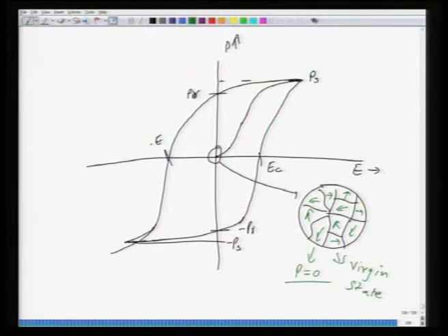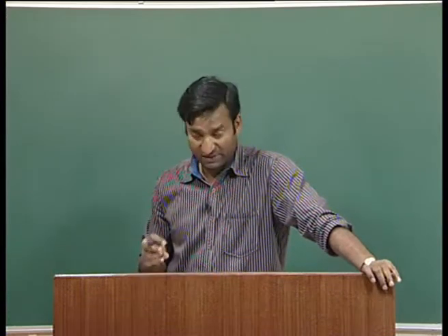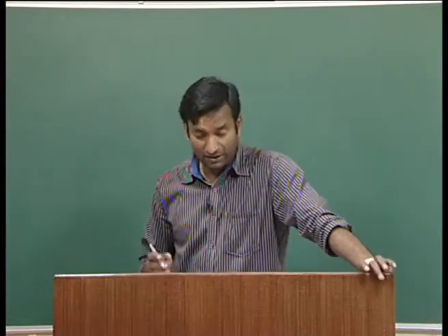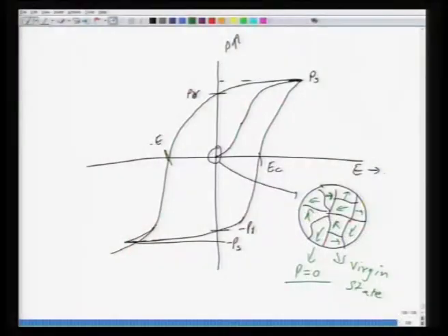But the moment you start poling it, you have formation of new domains. Now, this does not happen as, we will see, in magnetic materials. In ferroelectric materials, each time you do the polarization, it is always the nucleation and growth of new domains. You might think that domains which are favorably oriented would rotate in the direction of applied field, but no, this process is more energy consuming in ferroelectric materials than nucleation and growth.